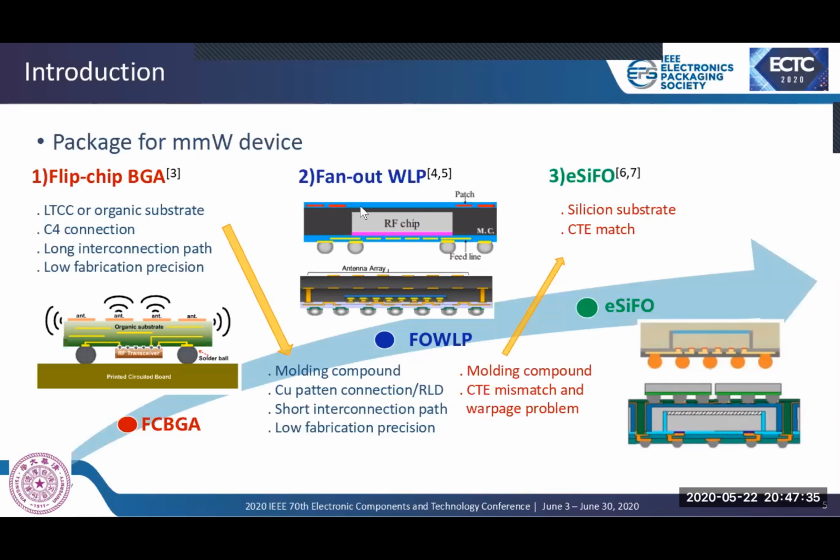In addition, to realize 3-dimension integration in fan-out wafer level package, traditionally a through-mold via is made, which is expensive and rough in dimension. However, the fan-out area in EC4 package is silicon, so through-silicon vias can be easily integrated, realizing high-density vertical interconnection.